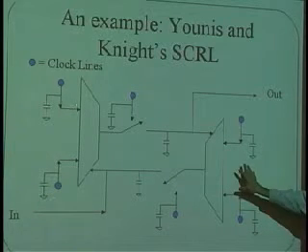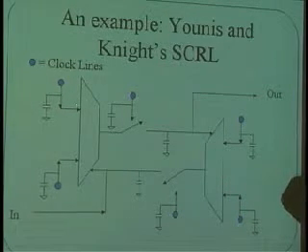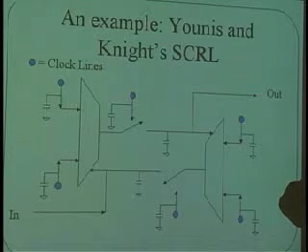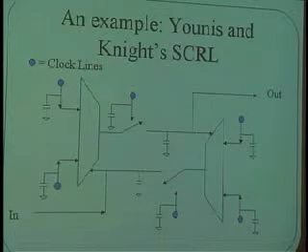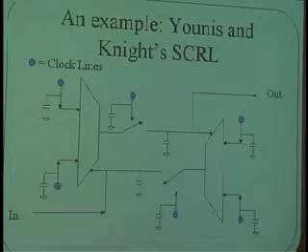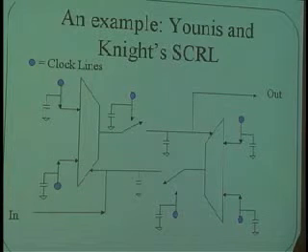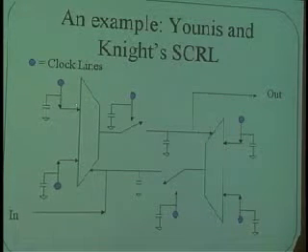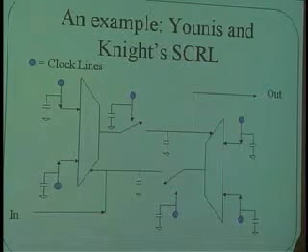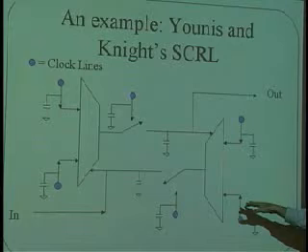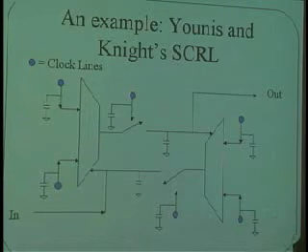Now, you don't need to, of course, know the details of how this thing works, but I wanted to show it to you as an example of how it might work. And again, the idea is that you never close a switch, you never connect a resistor across a voltage difference, like connecting it between the power supply and the capacitor directly. What you do instead is lower the power supply down to the value that the capacitor has, close the switch, and then slowly raise the capacitor value up. As a result, the resistance doesn't dissipate very much. The energy ends up going back into the system that generated the power in the first place.